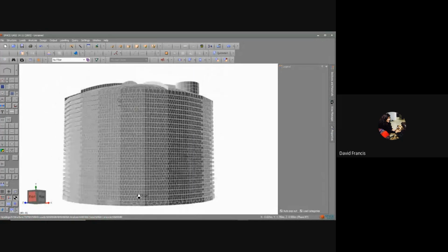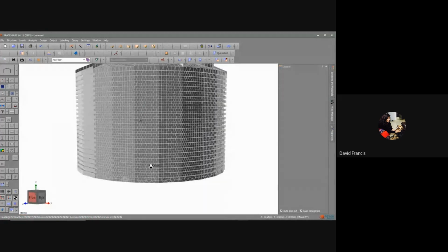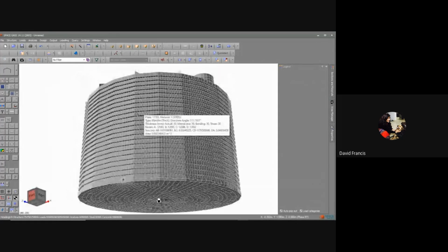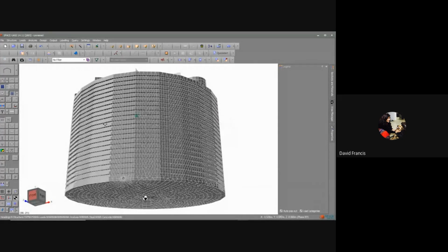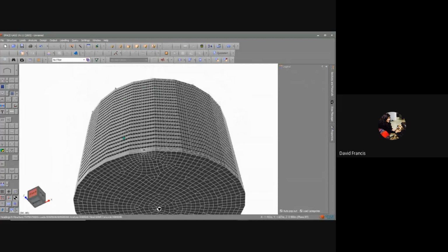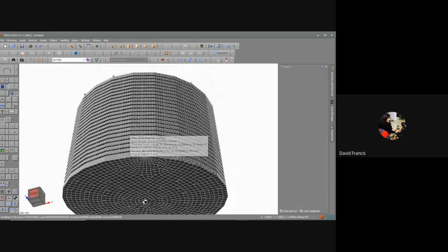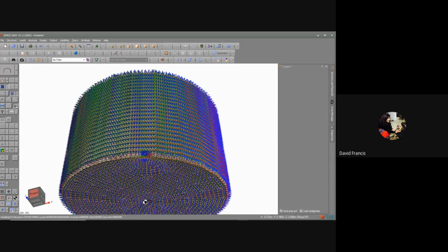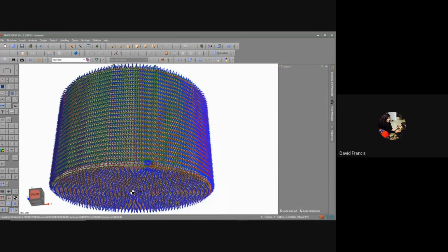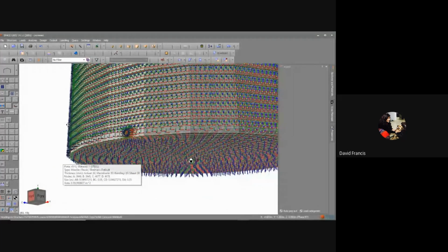So we could do a couple of fancy things with this now very quickly. I'd like to be able to analyze it and look at deflections and so on. Well, the first thing I want to do is on the base of the tank, all of these plate elements are there. If I turn on the local axes, these are the member local axes, you'll see that they're all pointing outwards and downwards on the bottom floor.